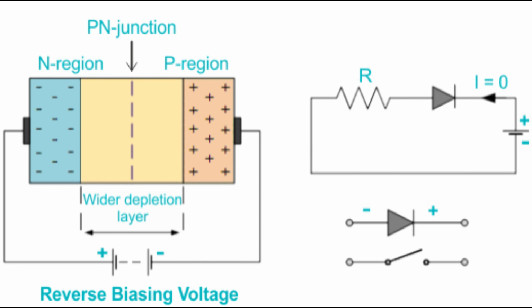The second test we'll be doing for the silicon diode is when reverse bias is applied. The barrier widens, preventing current flow. This test will pass when the meter's needle does not move. Reverse bias is accomplished when a negative voltage is applied to the P side and a positive voltage is applied to the N-type side.